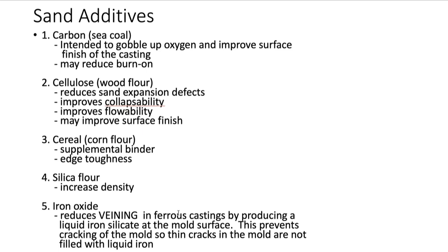Next, we can add some cellulose. That reduces the expansion defects. Why? Because wood flour will form little particles in between the sand grains.